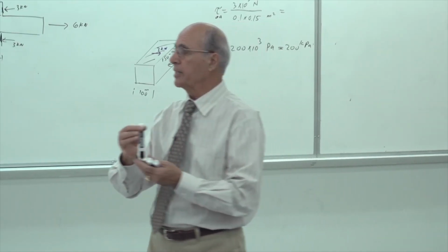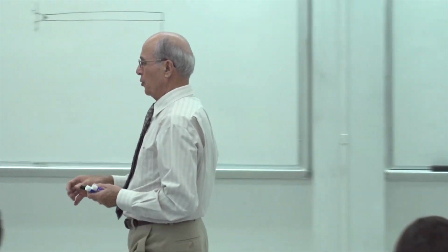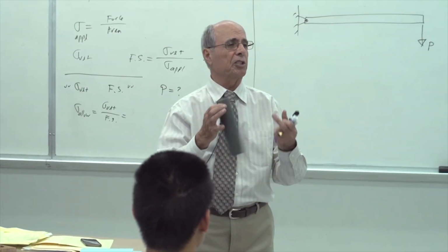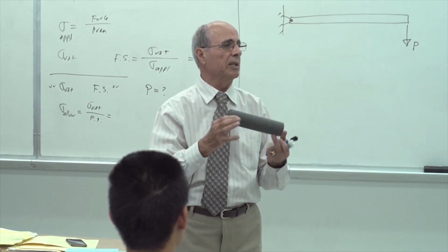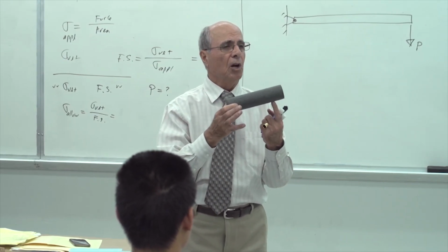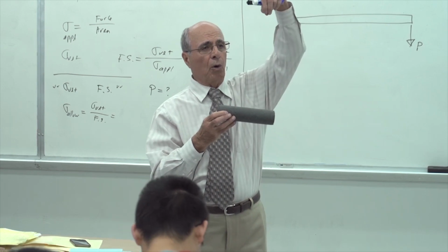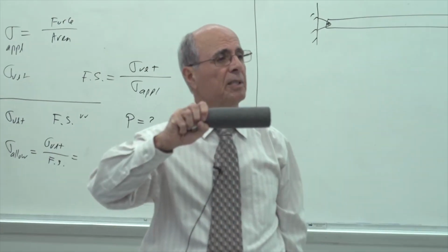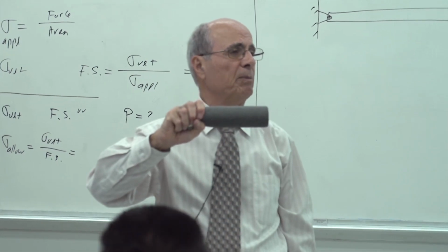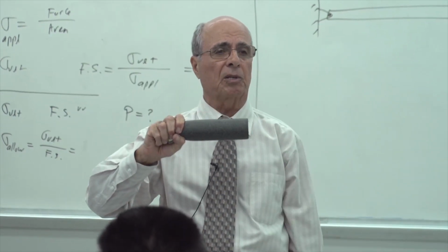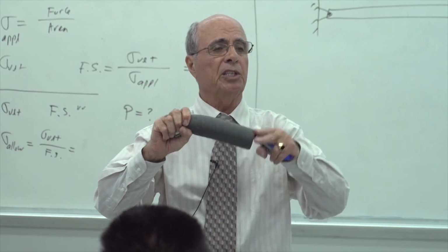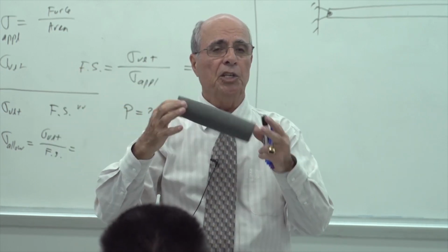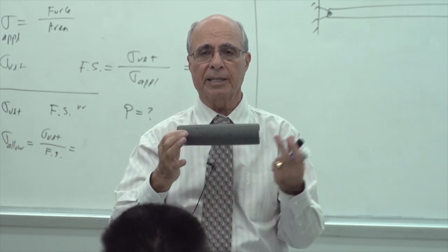pin connected. You have a rod here. You put a pin there. You hold it here with a pin. This is a structure. Is that correct? It just cannot stay there. I have to put something underneath it or hold it with a rope or something. In other words, if this was a fix, that would have been a different story. Everybody understands. In the fix, this is a complete structure, completely. I can load it here like a balcony type, sort of. You stand in the balcony and stay there. This you cannot do. Is that correct?